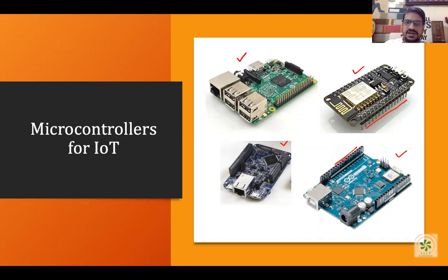The sensor is connected with the microcontroller and will become a sensor node. So there is a concept of sensor and there is a concept of sensor node. The sensor will just generate the data from the environment, and this generated data will be given to these types of microcontrollers. They have the capacity of storing the data, processing the data, as well as communicating the data. So when a sensor is attached to these sorts of microcontrollers, that is called a sensor node.